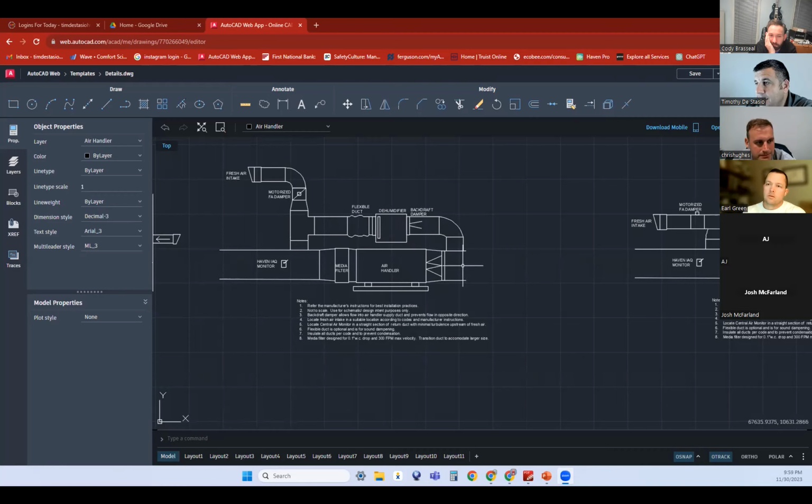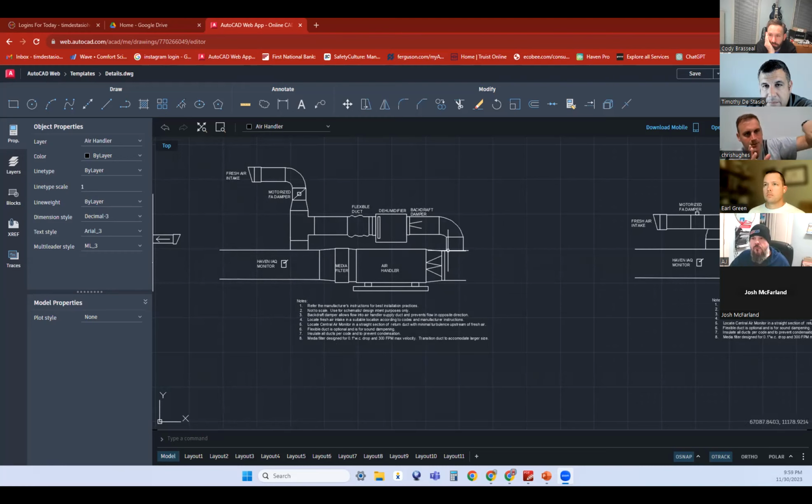So as long as you've got a decent static pressure, you're not running like a half inch on the supply side alone, you throw it to a 45-degree angle, it'll mix back in there. But Santa Fe gives you a diagram on that. Just go by that. And I've put in a scoop before, right where the supply goes into the supply. I've just mounted like a scoop. That way it's not just deadheading it. It's got almost like a scoop to run out. It's just a cheap, efficient way to avoid all that velocity pressure.